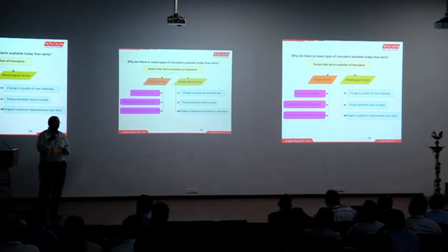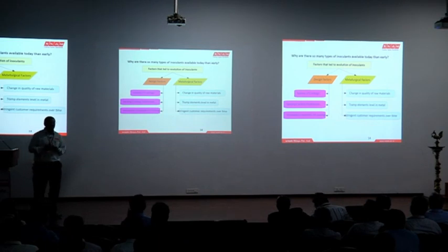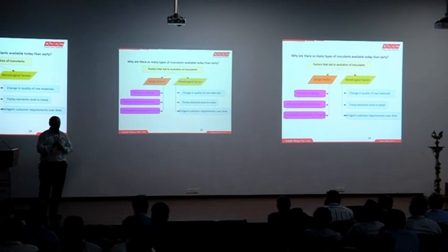Or when you have a machine shop attached to your own foundry, we start using borings, so that we get alloying elements back into our metal, and the requirement of ferroalloy addition comes down.